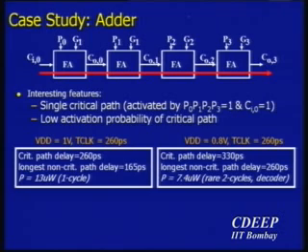So what it really means is that you have to pay in terms of performance penalty now. The percentage overhead in this particular case was about 5% of the 2-cycle operations or so. You can actually potentially improve it quite a bit. So what you're really doing is looking at carry look ahead operations, right? So you're trying to predict the carry ahead of time. In this particular case, there are some cases where you've got to play other games also. The important thing also to realize is the fact that you're scaling your supply voltage down, and that's where you're getting your advantage from.